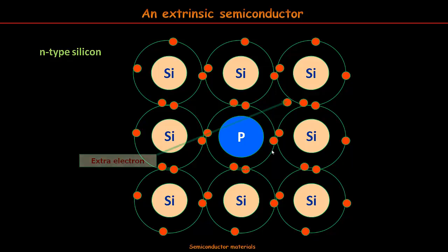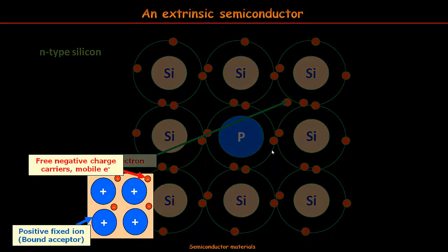So we can visualize the N-type semiconductor as a semiconductor network where free charge carrier pairs are continually generated by temperature, not interesting; a set of free electrons with no associated hole, free charge carriers that can conduct an electrical current; and a set of the same number of positive ions anchored to the semiconductor network. This is the way to represent that.